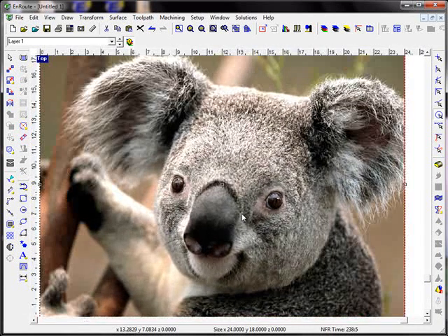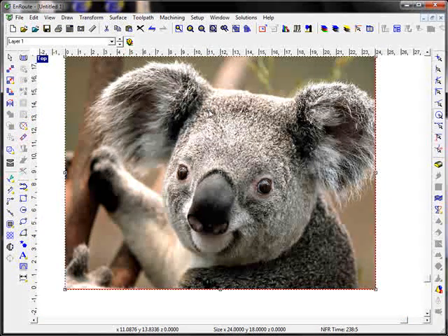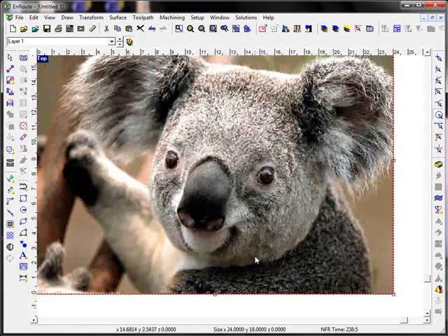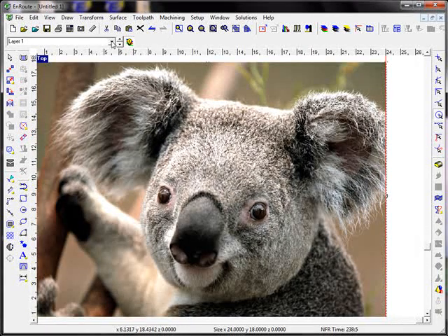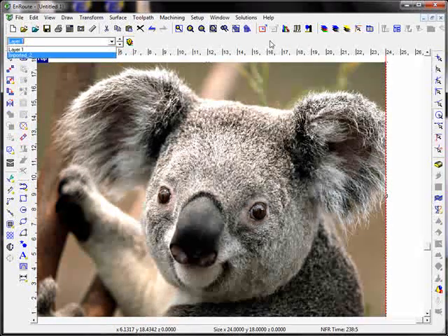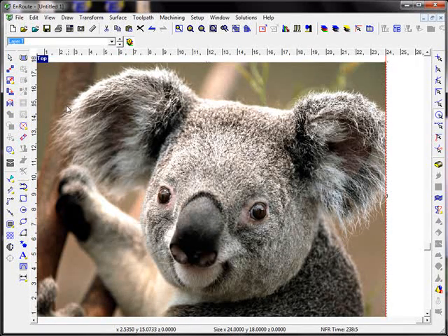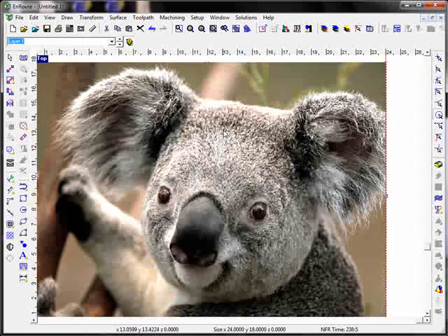So to take something like this and turn it into a 3D, we actually need to create some 2D geometry. I'm going to do that here by just drawing some profiles on screen. In my layers, I have two layers, layer 1 and imported. Layer 1 is on top of imported, so when I draw a contour, it's going to be on top of the picture layer. That's going to help me out there a little bit.